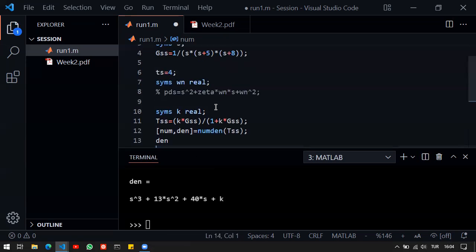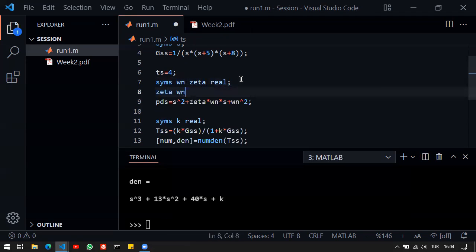And from the design point of view, let me also include this one here. I only know that the zeta times omega n multiplication should be equal to 1. So I have this equation here. So what I can do is I can directly plug in 1 into this part here. There's also 2 times here. So I can directly plug in zeta times omega n. But what I'd like to do is define zeta equals 1 divided by omega n.